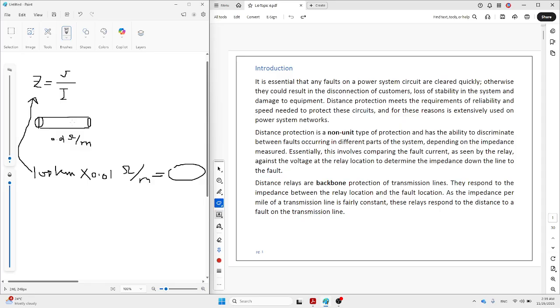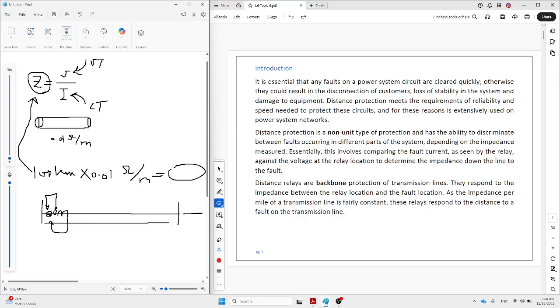Right now in the transmission line, if we can find the voltage using the VT, and the current using the CT at the relay point, we can find the Z. But this calculated Z is from the relay point until the end, meaning until the next lines. So we usually put the relay at the beginning. This is the distance relay, which is fed by a CT and, of course, a VT, so two are needed. So V over I can be measured from here to here based on Ohm's law, because by increasing the distance, the impedance increases: 1 meter is 1 times this one, 2 meters is 2 times, 3, 500. So you can find the impedance of this one.